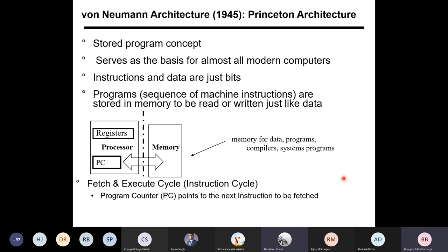Sir, so the instructions can be stored consecutively in memory, like the program counter. Yes, consecutive in memory, possible. Yeah, so the program counter just has to update to the next address, which can be done using a small constant addition to the program counter. Very good. And if we assume that all instructions are of the same length, 32 bits, 4 bytes in my machine, then what will happen?